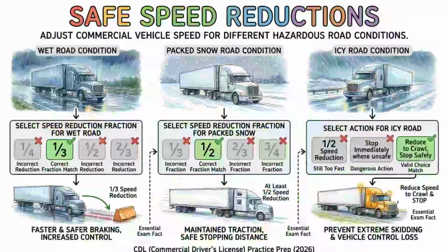Shifting gears in a commercial truck is completely different from shifting a small passenger car. Most heavy trucks use non-synchronized manual transmissions, meaning you must use a technique called double clutching to change gears smoothly. Double clutching involves pressing the clutch pedal to shift into neutral, releasing it, matching your engine speed to your road speed, and then pressing the clutch again to enter the next gear. Understanding the concept of matching your engine revolutions per minute to your road speed is vital for passing questions about transmission operation.